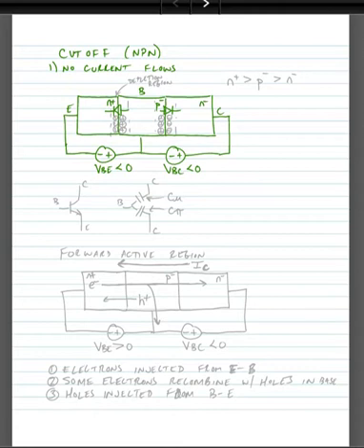Now when the diodes are off, what we have are depletion regions. In other words, charge carriers, or electrons, in the N minus region are drawn towards charge carriers in the P plus region, and they bind together to form pairs at the surface of this junction, or what we would call a depletion region. Because the carriers are all bound to one another, they don't want to move, and hence we have effectively an open circuit, no current flowing.